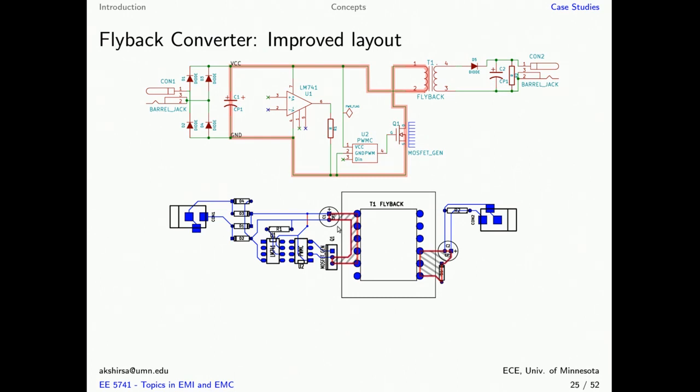Now let's look at what's going to happen to the op amp in our circuit, which is just representative of other circuits that may be next to the switching power supply. So earlier we saw that the current was flowing through this trace, and like in the previous example, this is going to cause a ground bounce at this node, which means that the power supply for this op amp is going to change and can result in noise coming at the output.